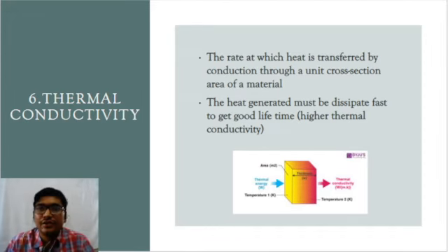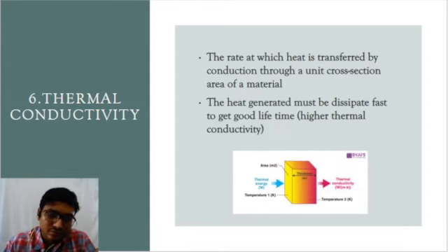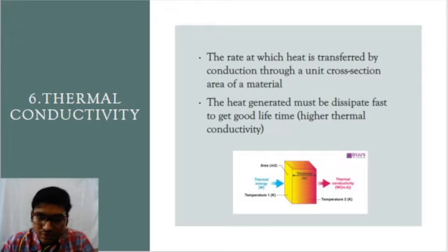The generated heat must be dissipated to the outer surface quickly. Fast dissipation of heat will protect the tool and give it a good lifetime. So the material must have higher thermal conductivity.